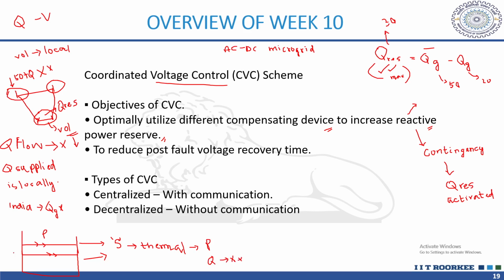By increasing the Q in the line, you are decreasing the amount of P that can be transferred using this line. Practically this is not done, but if some theoretical papers suggest this kind of work, it is never encouraged for Q to flow between areas which are geographically far away from each other. So, were you trying to say this or something else?